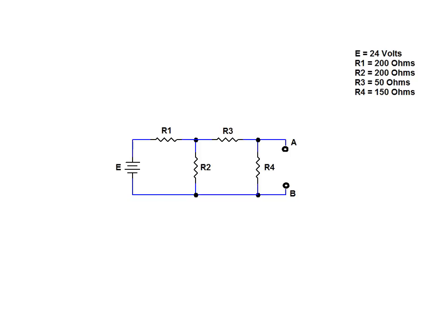Next, we create a short circuit between points A and B in the circuit. With the circuit in this condition, calculate the Norton equivalent current, IN, which flows through points A and B in the circuit. It is important to note that there is a short circuit around resistor R4, which effectively removes it from the circuit. There will be no current flowing through this resistor. In terms of calculating the Norton equivalent current, resistor R4 can be removed, as it has no part in determining the current flowing between points A and B.